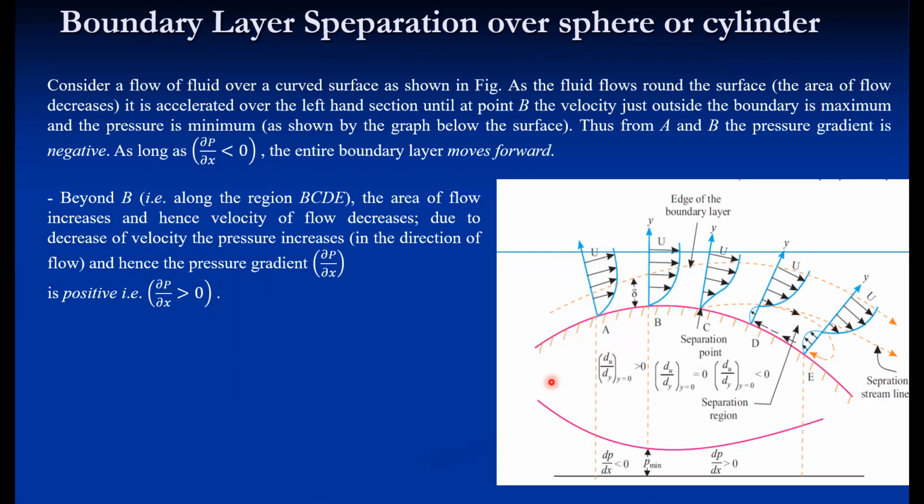If you see the pressure variation in this cross section, that is first a convergence section and then a divergence section, the pressure decreases, then it reaches the lowest level, and then the pressure increases. So this is the pressure variation. Similarly, the velocity variation is opposite to that: where the pressure is lowest, the velocity is highest, according to Bernoulli's theorem.